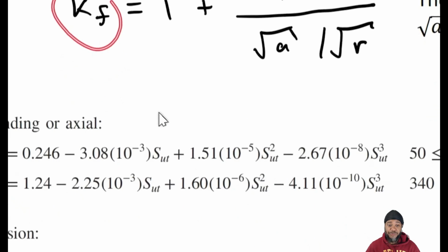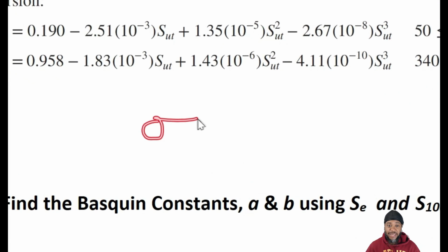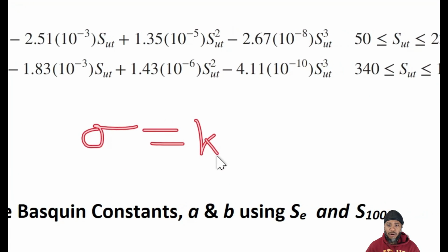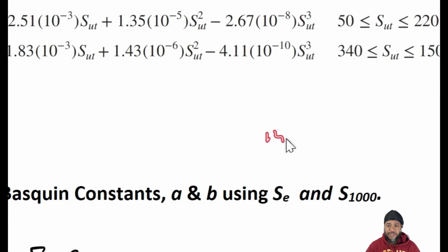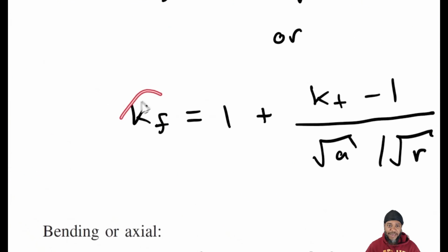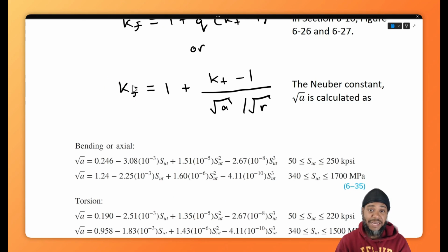Now we got this factor. What do we do with it? Well, the factor is applied to all of the stresses that are relative to the zero axis of fatigue. So our stresses are going to be multiplied by this factor for things like max stress, min stress, mean stress. And then we'll use those increased values of stress to calculate our cycles to failure, right?